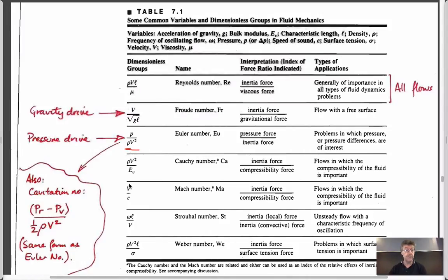The others that you'll have heard of in constant use are the Mach number, the velocity you're flying at relative to the speed of sound. The importance of that is that the way that we dissipate energy from structures is the same way that you're hearing my voice here. It's the speed of sound. The energy that's coming from my larynx, I guess, is being projected to you. It's traveling to you at the speed of sound. And so the significance of the Mach number is that if you're traveling at the speed of sound, then the energy that you're trying to dissipate from an aircraft or a flight structure can't physically get away.